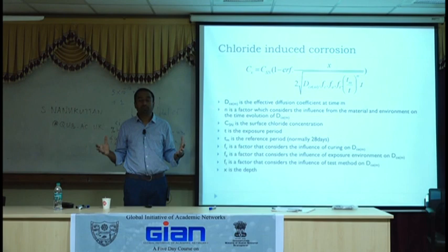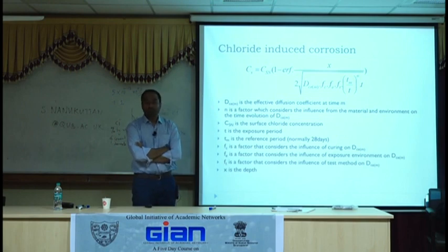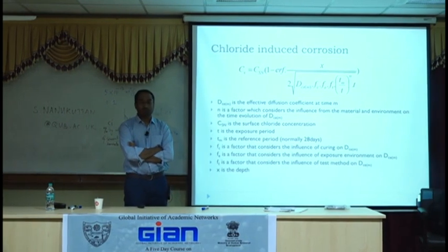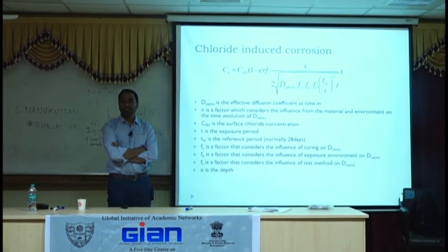All of these accelerated curing methods will help you to achieve normal curing that you cannot achieve otherwise. So for example, on a very dry open site, you will need some form of curing so that you get the normal curing that you would have achieved otherwise. For perfect curing, you just need to wrap it up with wet hessian and keep it moist for as long as you can. How long? As long as you can.